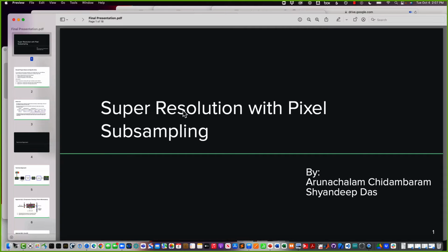There are a few things there, which is, one, our goal in that case is to reconstruct the signal. So if you sample at that rate, then in theory, if you do it correctly, you would be able to perfectly reconstruct the signal by taking those samples. So what's happening with standard Nyquist sampling is that our goal is to perfectly reconstruct, and all we exploit about the signal is its maximum frequency component, right? The knowledge about the signal is limited to that, and our goal is, like I said, reconstruction.